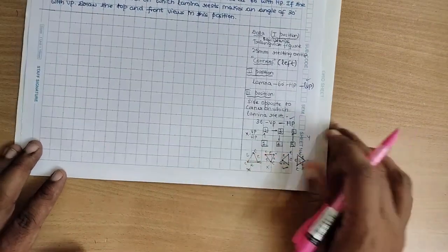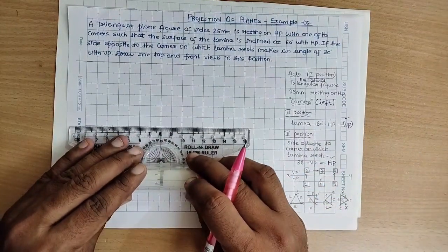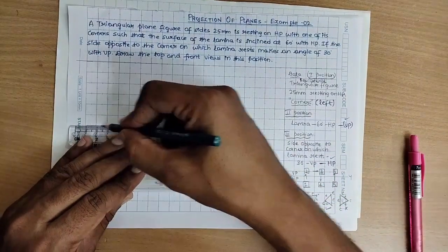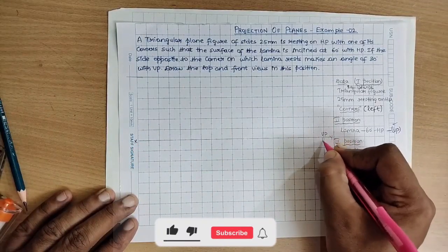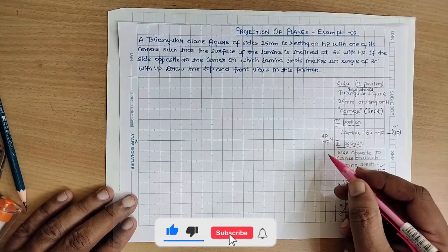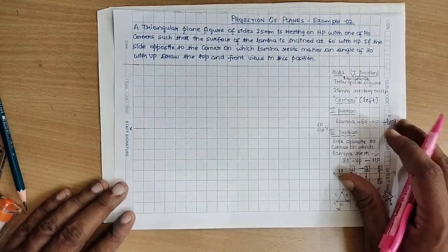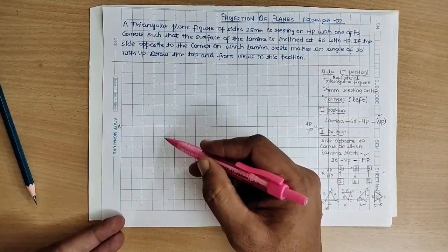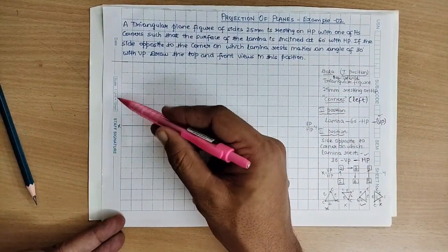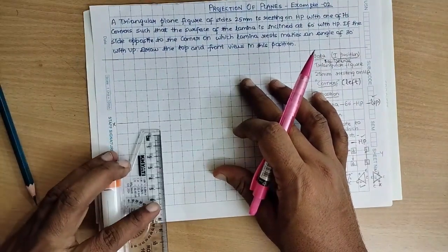Corner towards the left hand side of the observer. So make use of a scale. The first thing is to draw the XY line with minimum thickness. Call this X and Y, VP by HP. VP by HP indicates the projection of planes is in the first quadrant. Let us go for the first position. Make use of a scale here. Each grid is supposed to be 10 mm. As clearly mentioned, 1 unit is equal to 10 mm. For 25 mm, let us cover 2.5 grids.